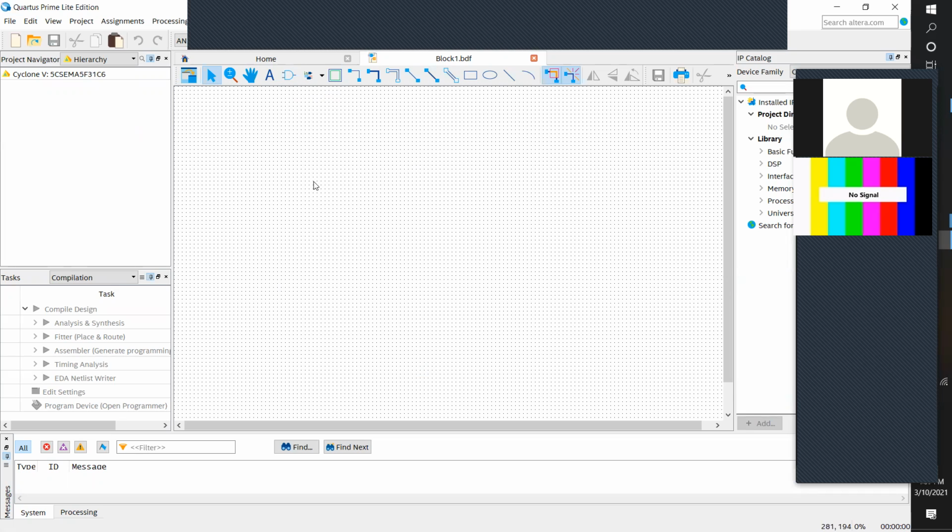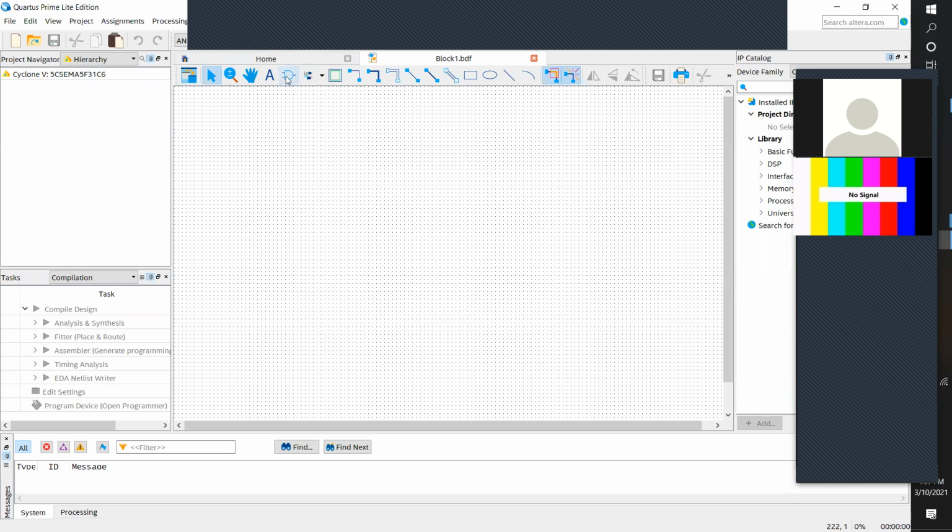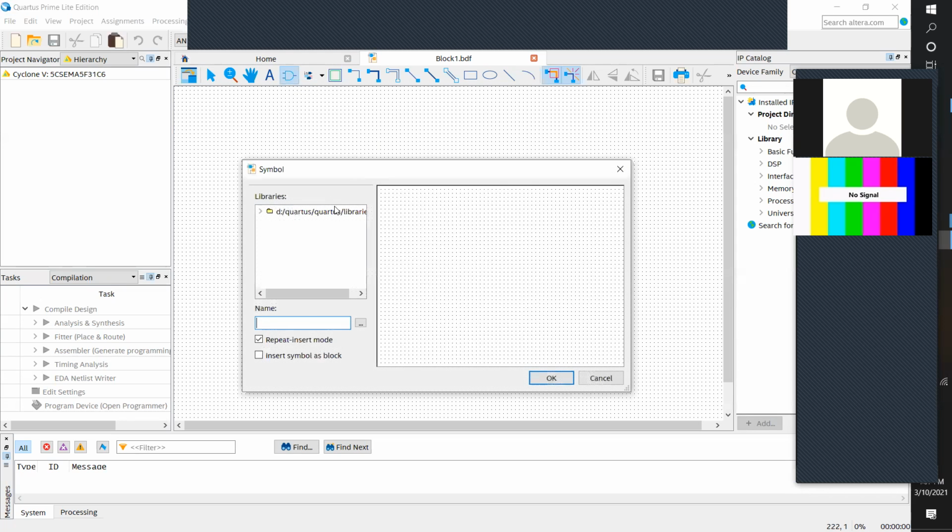So now I will just show you how to find a component here. See, this is a little icon here, the AND gate. First thing you need to know is what do we need? Like in the half adder, you might need the AND gate, OR gate, or even XOR gate. Here, for simplicity, we only use an AND gate. There are many kinds of AND gate.